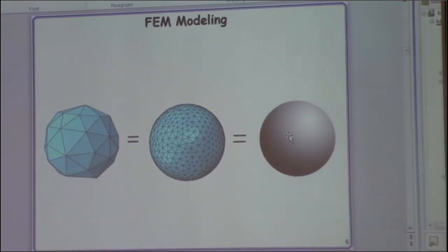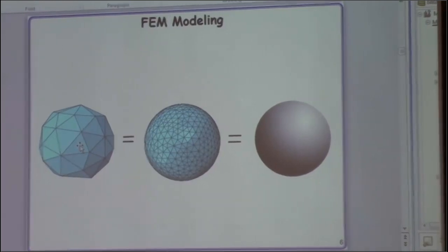And if you want to know the stress or displacement at any point on this model, it's hard to calculate directly. So what do we do? We discretize it into elements, and then for stress we can calculate the stress at each integration point, and if you want to know the displacement result, we can calculate the displacement at each node. And then for the area in between, we can do the interpolation. As this discretization and interpolation are just an approximation, it cannot give you an accurate result.